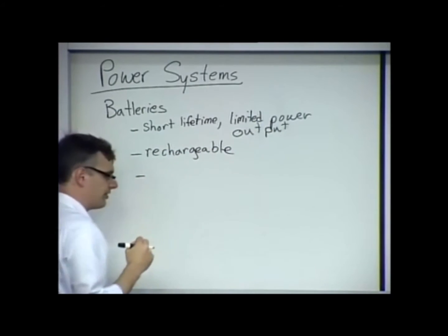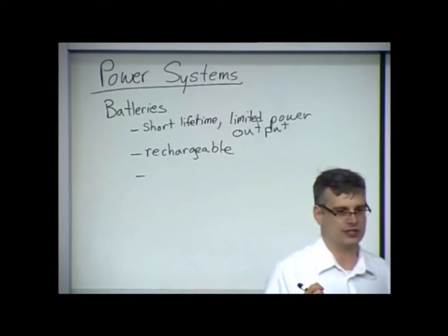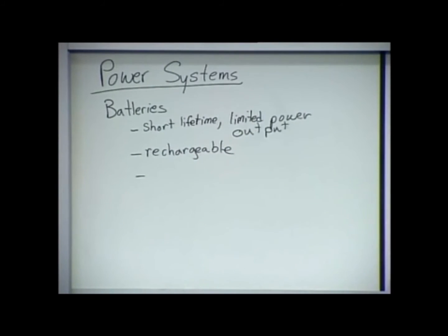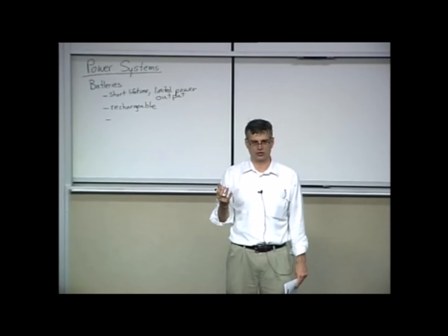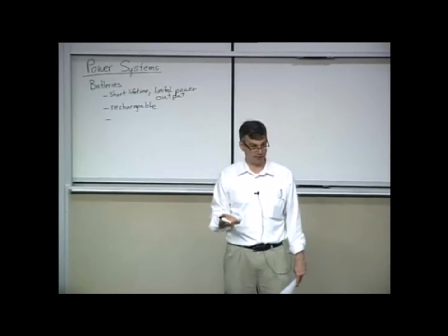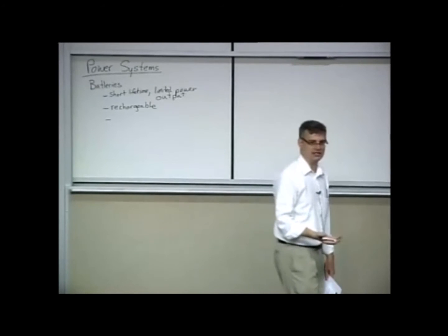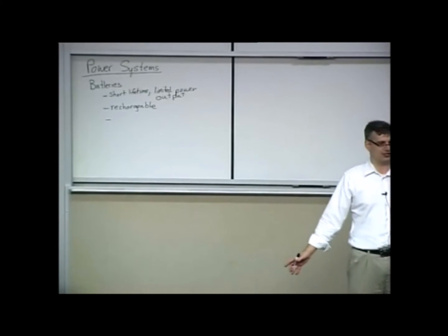And one thing that you don't think about in space is that battery chemistry is heavily temperature dependent. And so the battery is usually encased with some sort of thermal and radiation protection so that it's not exposed directly to the sun. However, if you're in the shadow of space, the temperature plummets, and you're well below freezing.